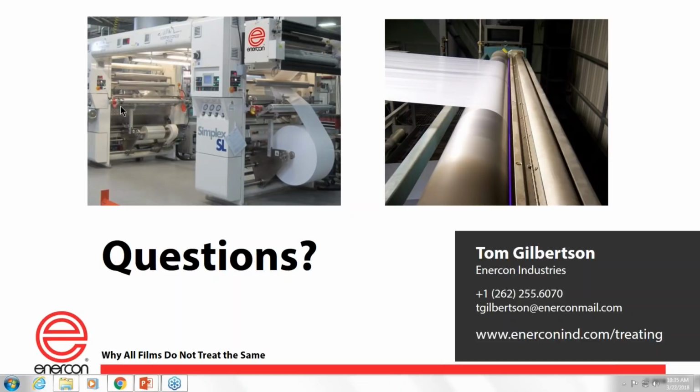So here's a question: how long would corona treatment be effective at the surface of Kapton polyimide film used for printing later on? Well, it's a great question. Typically, Kapton films are actually pretty receptive to corona treatment, and the dyne levels are relatively stable. Although that said, the devil's in the details there. It depends on what kind of chemistry you're applying, whether it's a solvent chemistry or water-based or energy curable, whatever the case. But just in a general way, Kapton material is pretty responsive to corona treatment.